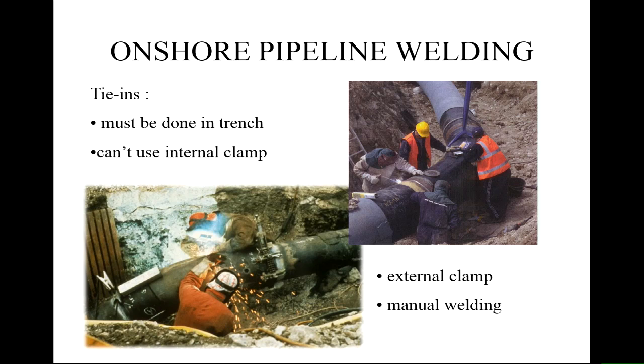What's not necessarily so good, and you can see an example here, is the welding sticks sitting in a box. It's open, so if this was wet, they would be absorbing water. So as long as that box had just been opened and it was being used very quickly, that's probably all right.